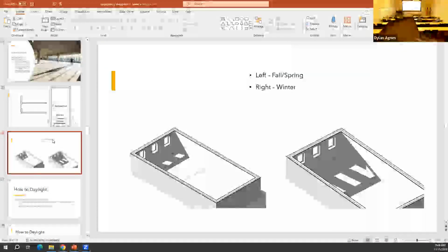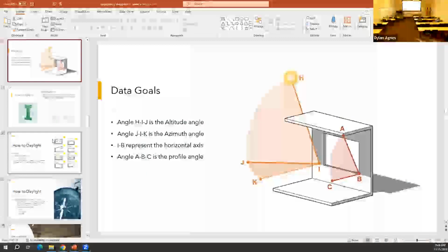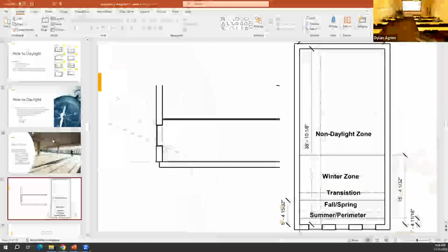And so, yeah, you can basically draw it on there. And so instead of following this guideline to track the actual position of the sun and how it's going to affect your building, you would instead apply the IECC definitions for, in this case, side lighting. So, taking from the bottom of the floor to the top sill of the window and using that as your height, so that's your length. And then your width is 2 feet on either side of the window until you run into an obstruction. And so basically, you would draw that, and that would be your daylight harvesting zone.